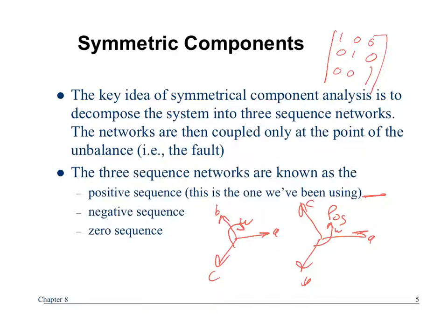Does that make sense? You're just swapping them around. So this is called negative sequence rotation, because to get that ABC again, we have to operate the vectors in the opposite direction. This is actually what happens when you do the math out. The sine waves are operating in the opposite direction to get their response.